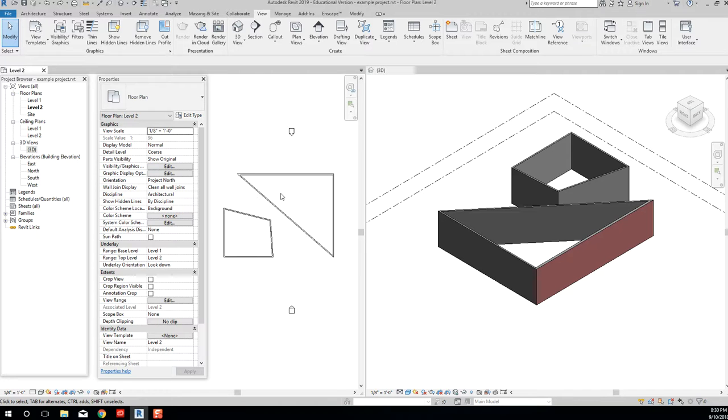I can double click my middle roller twice very quickly, click, click, and I get what's called a zoom extents, okay? A zoom extents will bring all of the geometry shown in my model space to the extent of my drawing board. So if I have 50 little buildings here and I do a zoom extents, it zooms out to show me everything that I've drawn, okay? So I can zoom in, I can zoom out, and I can double click my middle roller twice and do a zoom extents, okay?